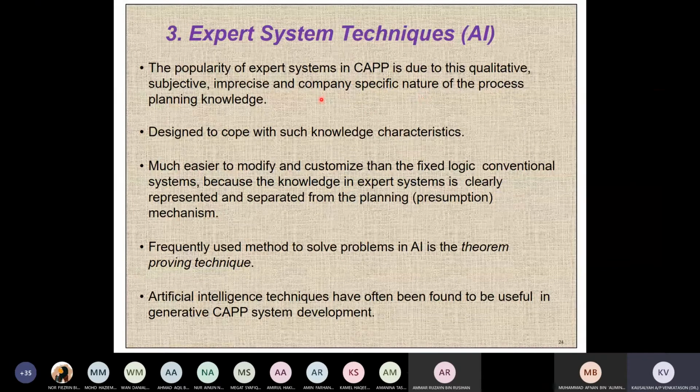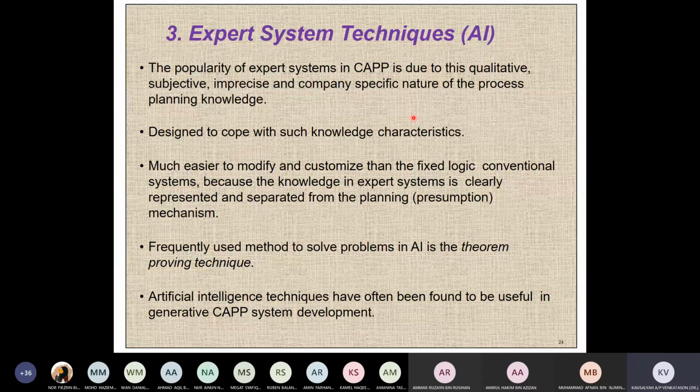Let's say we have a robot which is supposed to do a pick and place in a production line. It's supposed to detect any errant products. The robot will look at, let's just say, products which come out with extra heat. How is the robot going to understand that? You have to attach a heat sensor to the robotic arm, and the heat sensor has to be programmed with a certain range. If the part that comes out falls into the range of error detection, then the robot will not pick it. Otherwise, it will pick and place. So that's a very basic example I'm giving.